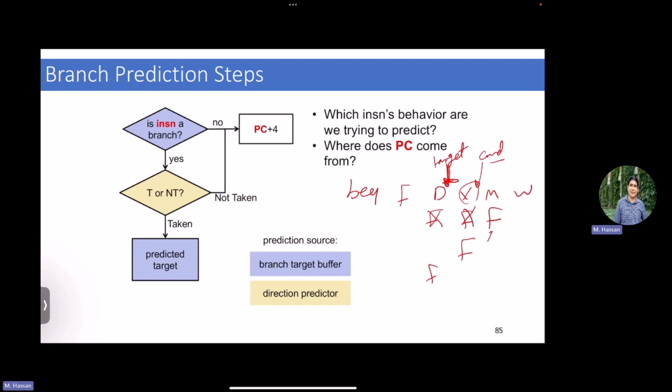For example, the BTB is a simple hardware component that in fact solves the problem most of the time because you cannot do better. So this is almost a dead area of research, because I keep a simple table. I have the program counter during the fetch stage, and I have a flag telling me whether it's a branch and, if it is, what the target address is. The harder part comes later on in the pipeline, whether the condition is true or false. In that case, I need more circuitry and more intelligence, which is done by the branch predictor. Maxim implements the G-share branch predictor, but in the tutorial document I shared with you, they discuss all the possible ones.